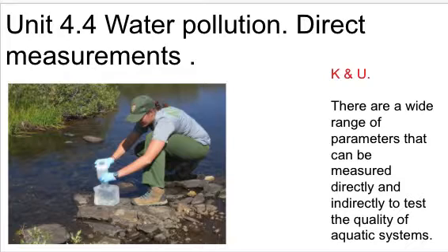For dissolved oxygen, typically for a very healthy water quality, we'll be looking at 75% plus dissolved oxygen. 10 to 50% will be considered as polluted. And less than 10% oxygen concentration will be associated with raw sewage.